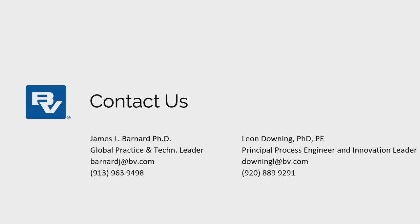Let's see. Next question is, is this technology proprietary? Any chemicals involved in the project? It's not proprietary. I mean, there was some patent on one configuration at one point, but doing a sidestream RAS fermentation tank is not proprietary. As far as chemicals go, it depends on the facility. Some facilities will do some chemical polishing. Others may need a lot of extra carbon. I know Micro C is a commercially available one that folks have used, but you can also just use waste carbon products. But yeah, not proprietary.